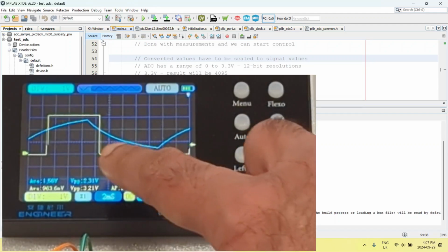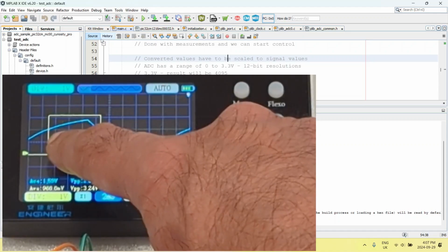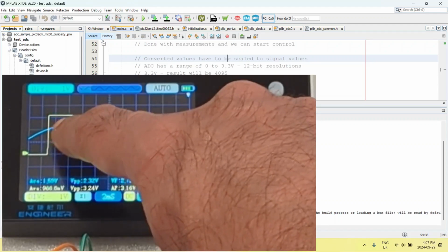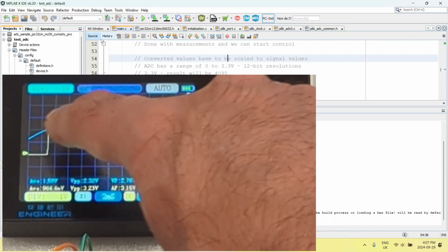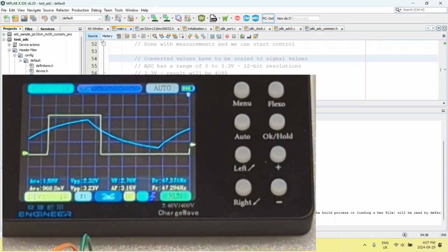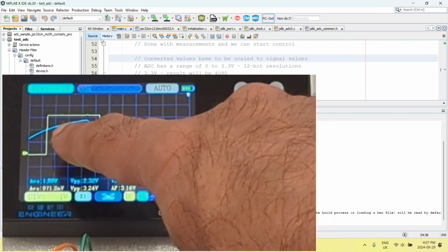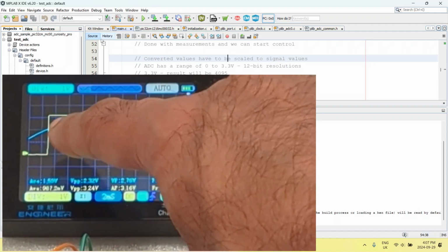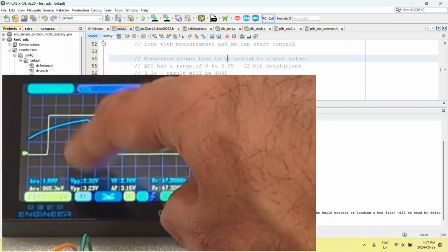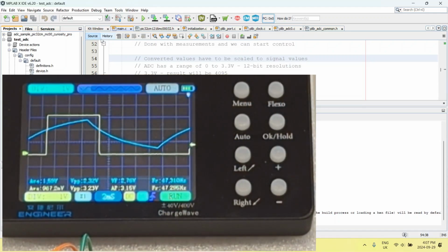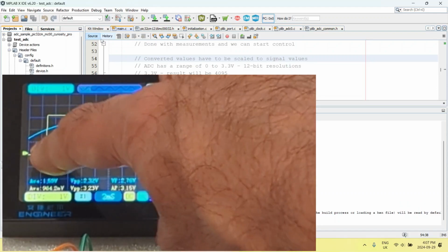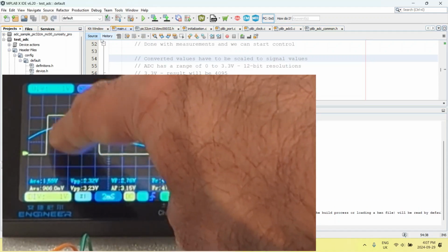And if you take a look, you will see here that it is very clearly when this blue waveform crosses the second division here, that is when the pulse goes high, the GPIO pin. So this clearly shows that our comparison that is happening in our control code is matching with what we are seeing in the oscilloscope. So you see here the blue waveform is actually crossing 2 volts, because remember our division, the division for both channels is 1 volt per division. So which means the blue waveform is crossing the second division from our reference, and at that moment you will see that the pulse is going high.